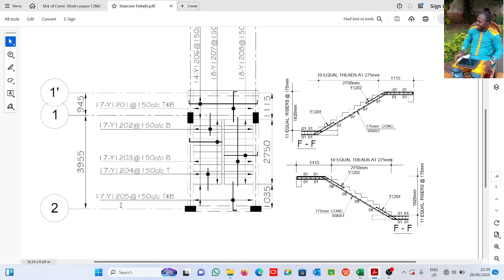I will explain something here again. If it were to be 30 top and bottom, and this 17 means top and bottom. If not, they would have put 34. Except the structural engineer gives a further instruction: don't say it is top and bottom, you multiply by 2. The structural engineer will put it as 34. Top and bottom is 17. Don't go and help them and put 34 without a request for information.